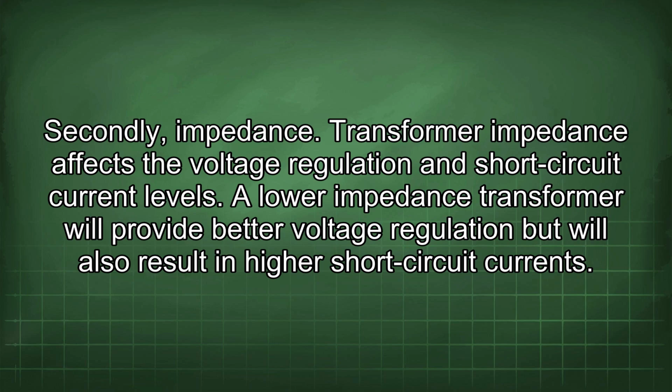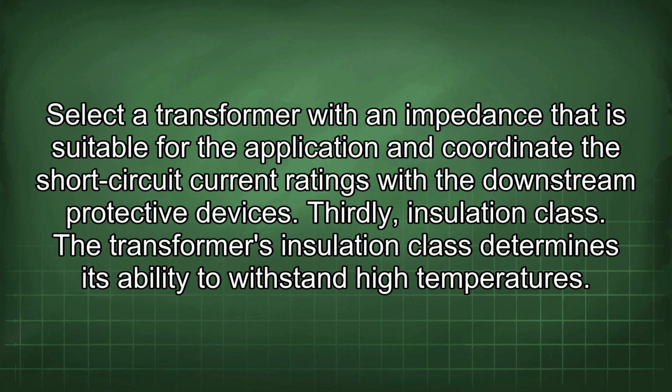Secondly, impedance. Transformer impedance affects the voltage regulation and short-circuit current levels. A lower impedance transformer will provide better voltage regulation but will also result in higher short-circuit currents. Select a transformer with an impedance that is suitable for the application and coordinate the short-circuit current ratings with the downstream protective devices.